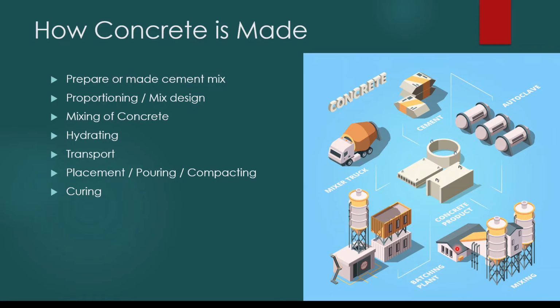Then once you have the mix design, you do the mixing at the batching plant. We add the cement, we add the coarse aggregate to the bin, then it is rotated and mixed. During this process we add the water. Then the water also gets added in the end of mixing. So if we are using an admixture now,